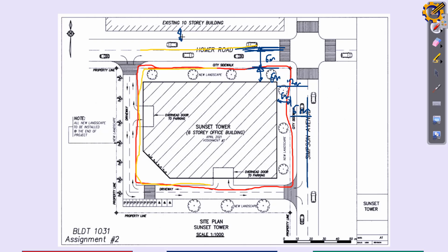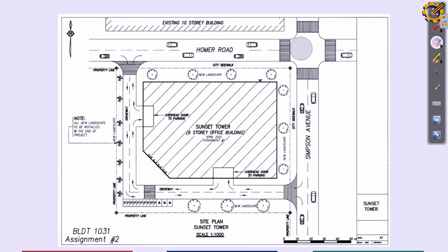So you don't build your house closer to the road, even though you are the owner of the land. They sold it to you as 60 by 120 or 100 by 50 feet of land, as the case may be. No building regulatory agency will approve your building plan otherwise, and that is the reason why they want to see your site plan. On the site plan, you will have shown the setback line and everything. With that, they can now approve your building for you.